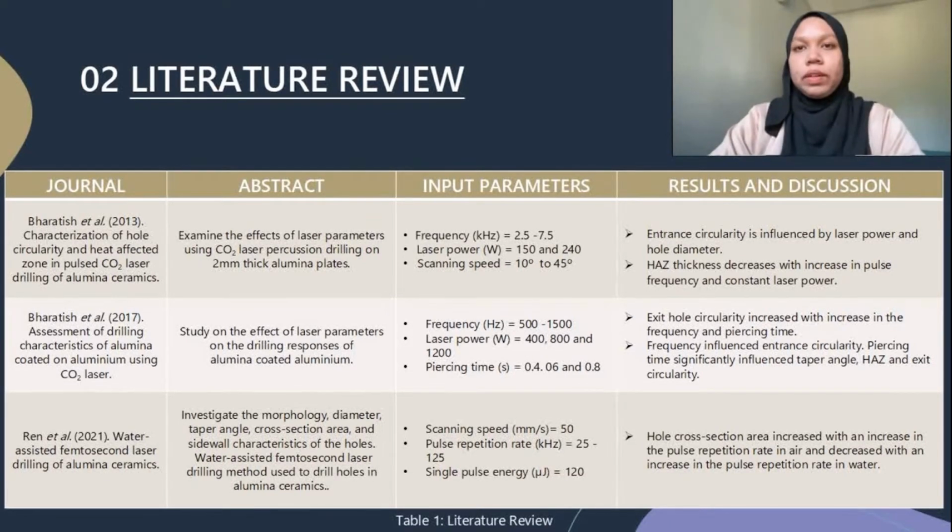The third journal, by Rand, investigated the morphology, diameter, taper angle, cross-section area, and sidewall characteristics of the holes. The water-assisted femtosecond laser drilling method was used to drill holes in alumina ceramics. The machining parameters used are scanning speed, pulse repetition rate, and single pulse energy. The results stated that the whole cross-section area increased with an increase in the pulse repetition rate in air and decreased with an increase in the pulse repetition rate in water.